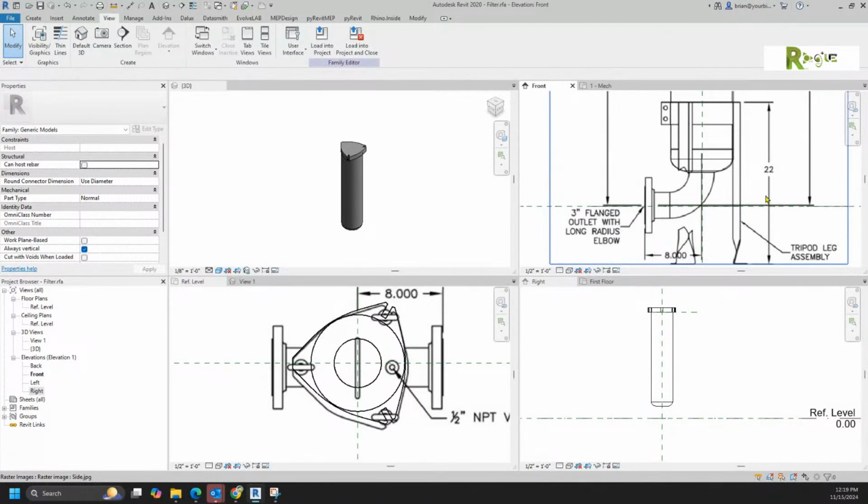And the only way you can do that is to put a nested family in there so that you can rotate that nested family. I can't think of a way to flex that to go the other direction. So you build another whole separate family and then load it into this family? That's what I'm seeing. I'm seeing another family here.